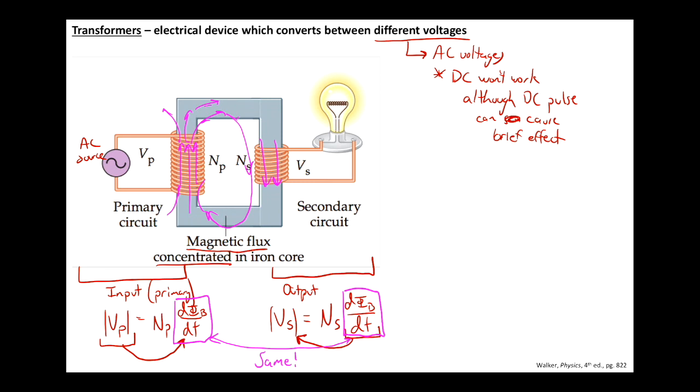Overall, whatever flux is being created in the center of this is really close to the same as what's going the opposite direction in the really close nearby coil, which allows me to connect these two equations. Keep in mind, is it quite that perfect? No, that's okay. It still helps us get the concept. There's going to be some losses there. This might be to take the two and overlap them. You could insulate them in some way so that one coil is inside the other, and then they're literally experiencing the exact same flux. But hopefully this diagram will give us the basic idea.